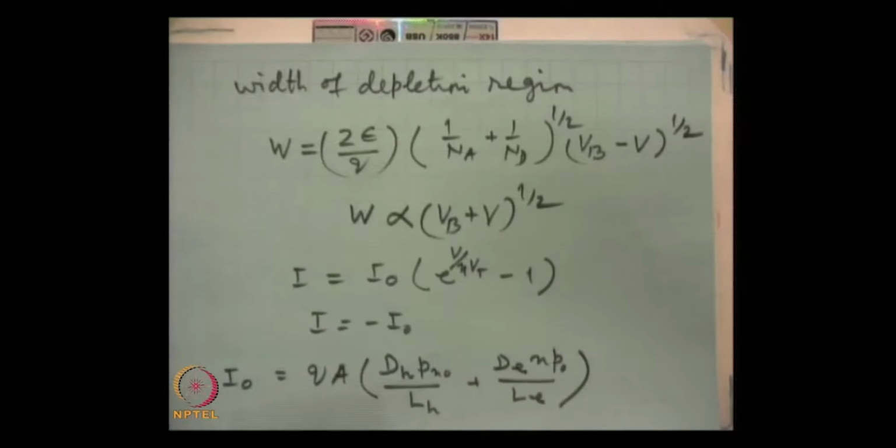So, this is all about the IV characteristics of the PN diode, the currents in the forward direction and the reverse direction, and how the depletion width varies with the applied voltage. It will decrease with the forward bias and increase with the reverse bias. Always remember the resistance of the diode in the forward direction is extremely small, just a few tens of ohms, but in reverse bias a very high impedance of the order of megohms is obtained.